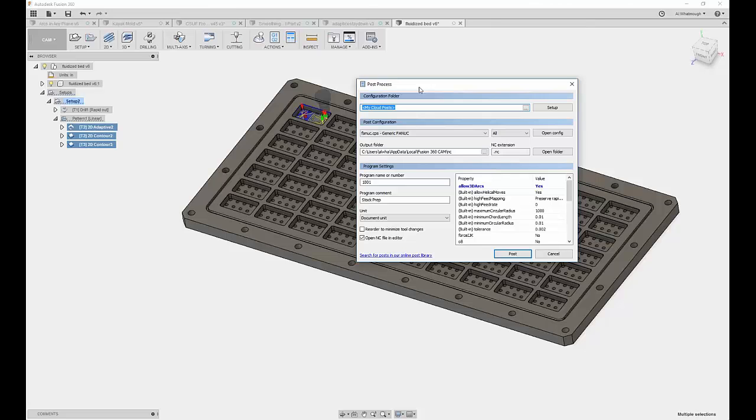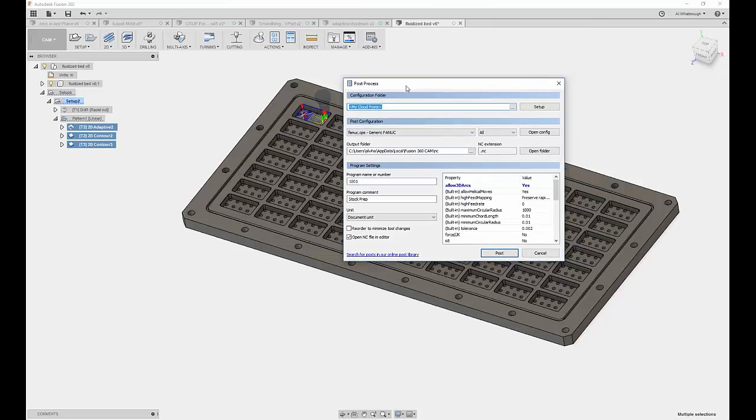So I'm going to go ahead and use the FANUC post processor. This is the one we got off the post web page. If I scroll down, we're going to use this 3D arc thing later. That's a later conversation. You'll see some options. A lot of people miss looking at all these options. There's a lot the post processor can do, and a lot of people that are used to other CAM systems assume that a post processor sort of has a defined set of outputs. Because our post processors are almost an API, there's a lot of things that can get programmed into them, and then user-defined switches that can be set that can really fundamentally change how the post processor operates.